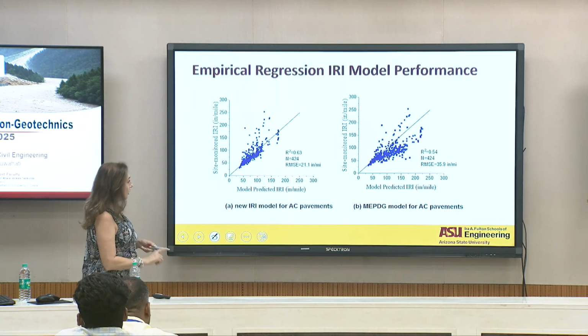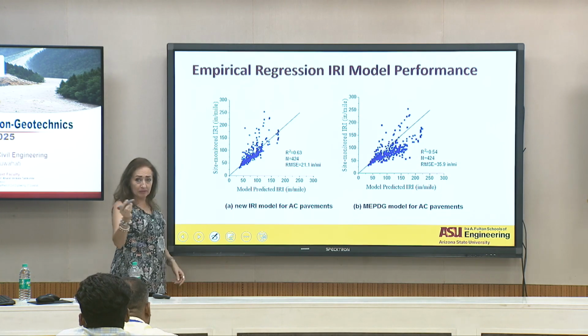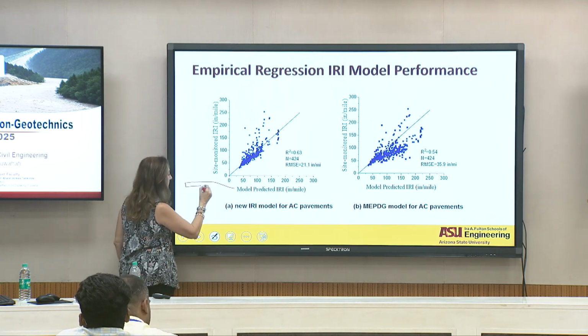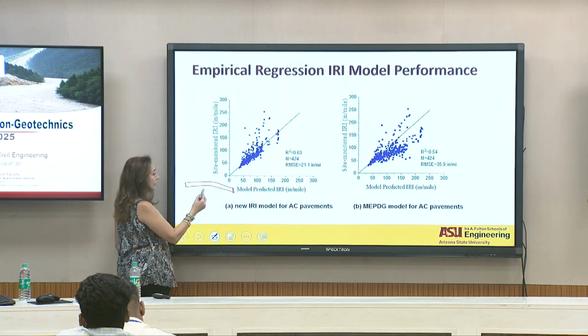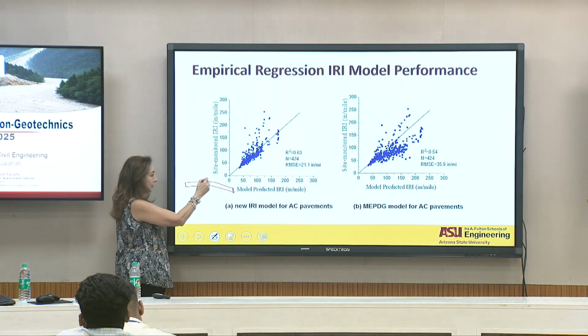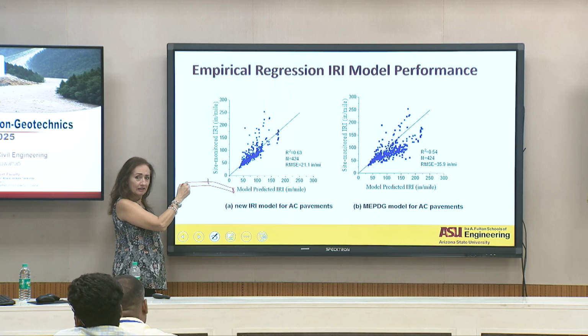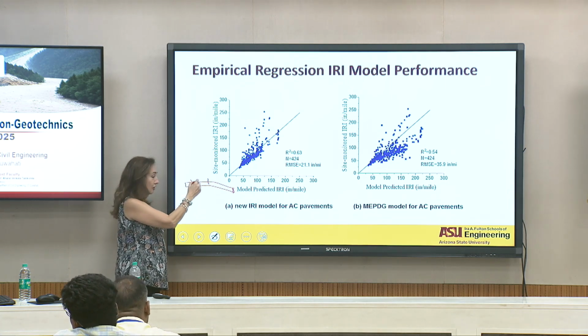Yeah. If you check a pavement in the LTPP, you're going to have deflection measurements at the crest, deflection measurements on the outside wheel path and inside wheel path, you know more than me.